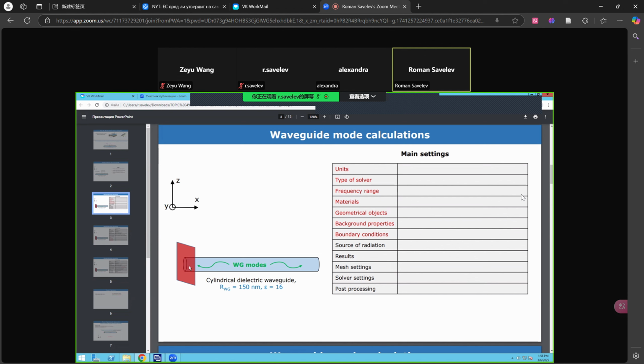So we're not going to consider the very low frequencies when the evanescent tails have, let's say, 3 wavelengths in size. They're typically something around lambda over 4, lambda over 2. So the size of the waveguide port should be chosen accordingly. Something around lambda over 4 typically is enough, maybe slightly larger.